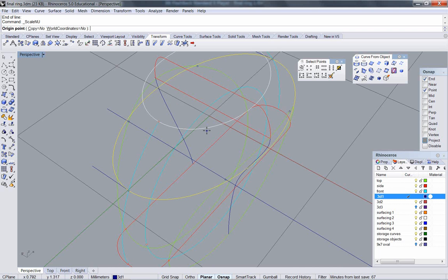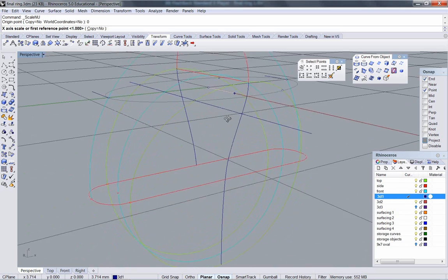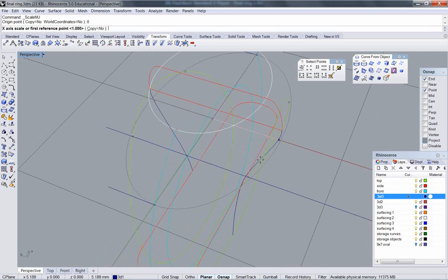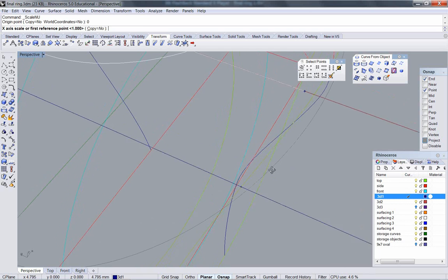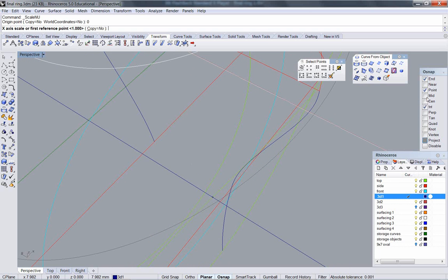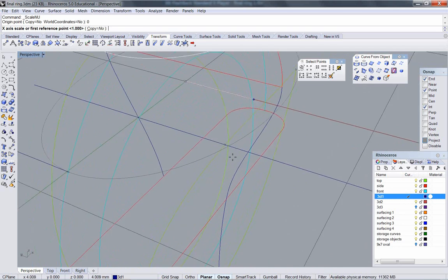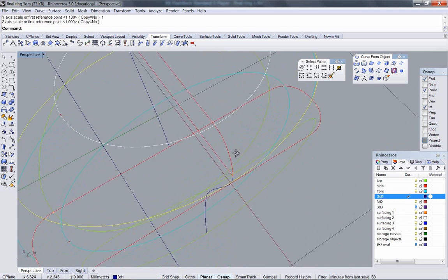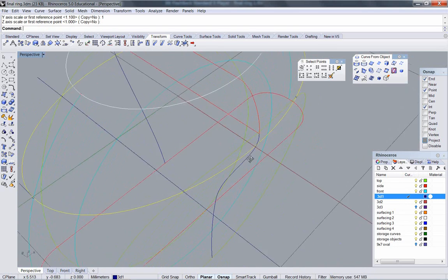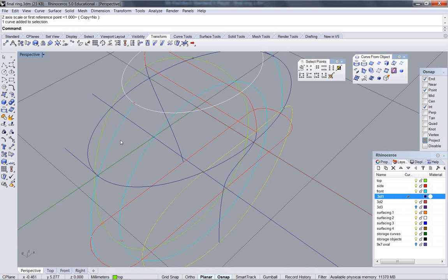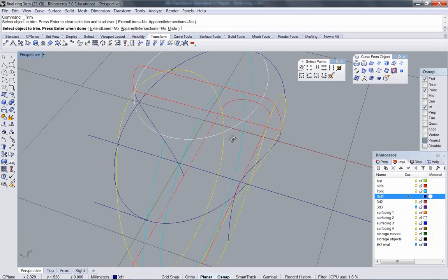Once again, having the custom C-plane built onto the surface that was centered up allows me to use 0 enter to do a lot of my scaling and whatnot. Intersection to point. 1 enter. So now I know it's intersecting right there the way that I want to. I'm going to trim the outsides off.